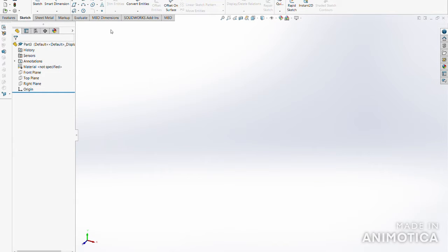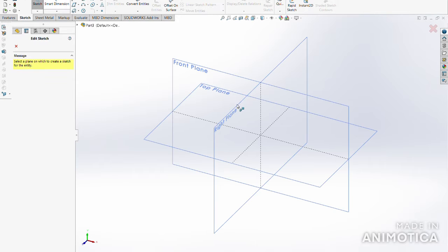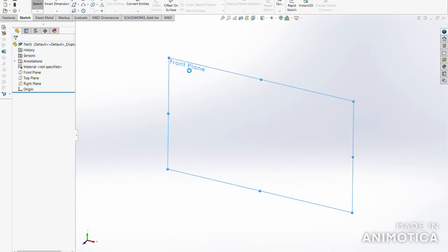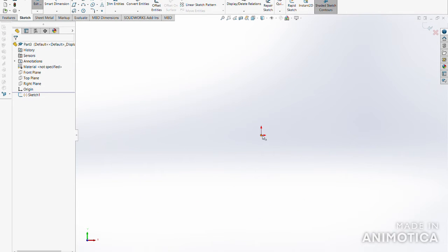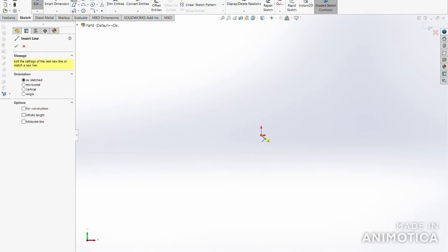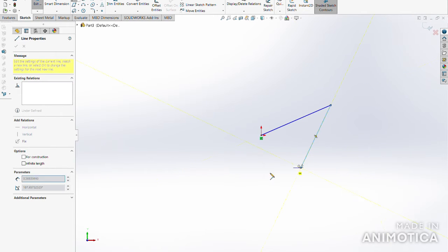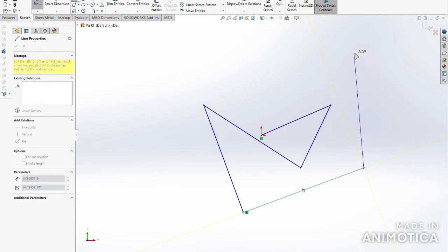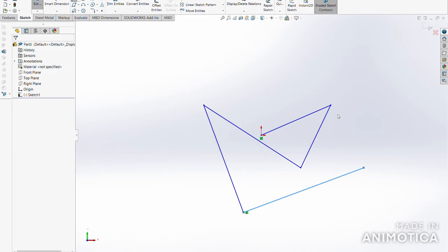So now that we're on SolidWorks, I'm just going to show you. So you make a new part, and you're going to open the sketch bar, and then you're going to click sketch, and you have the choice between 3 planes here, so it doesn't matter which one you choose. I'm going to do the front plane, and you can see this is the center, which I'm going to draw some of the sketches on. And so here's your most basic form of sketching, the line. So say I start from the center, I can draw anywhere I want and just make whatever kind of design I want, right?